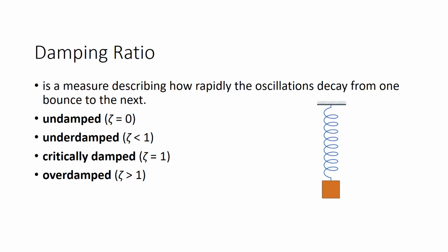An underdamped system will oscillate through the equilibrium position, while critical damping returns the system to equilibrium as fast as possible without overshooting, and an overdamped system moves more slowly toward equilibrium than one that is critically damped.